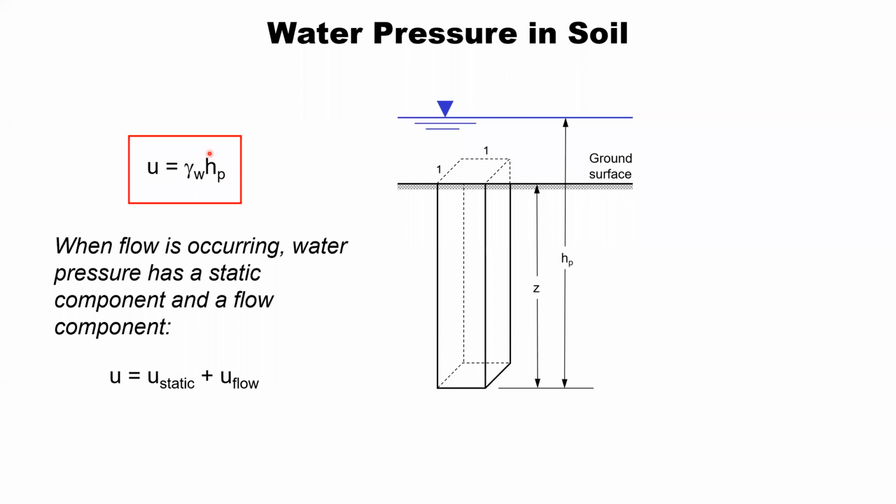That friction can be called a drag force. So you've got water flowing around these particles, and as it flows around them, shear stresses are developed at that interface, and that shear stress is acting to pull, or push, if you will, the particle in the direction of flow.